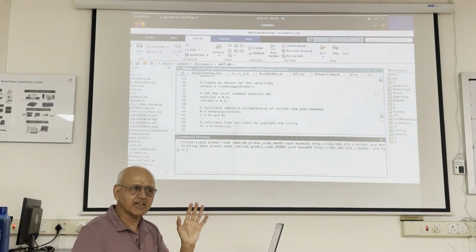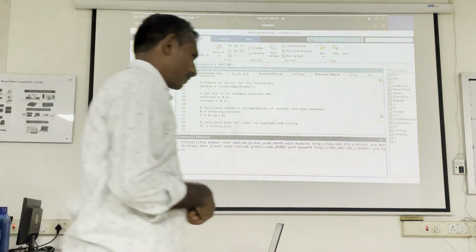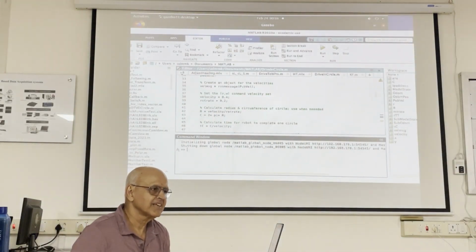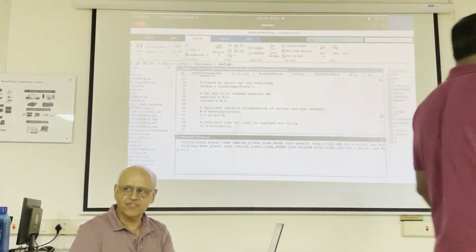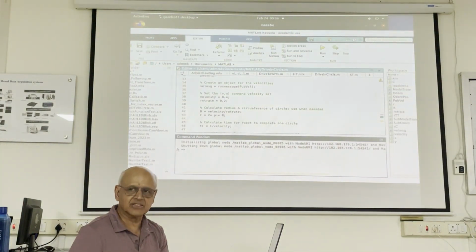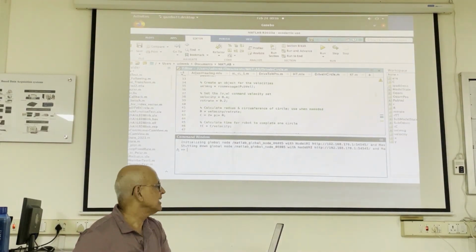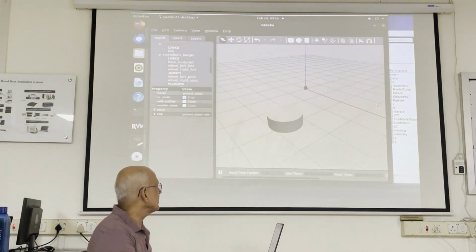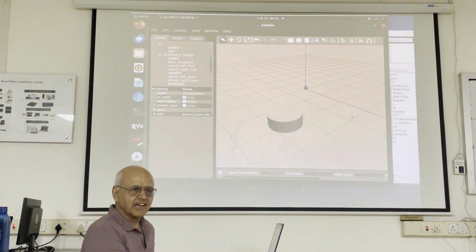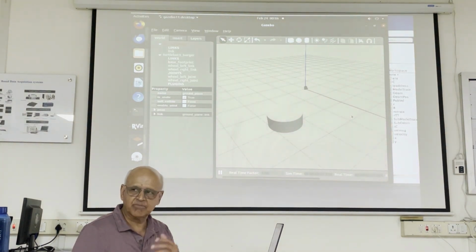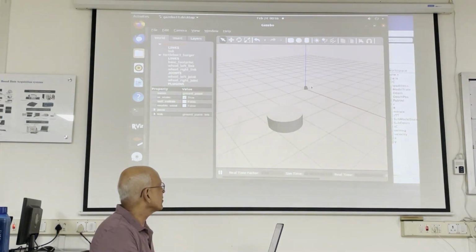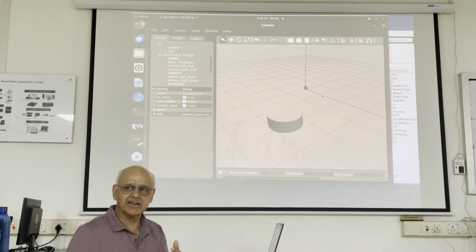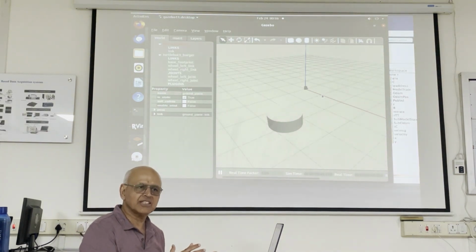But I've seen robots from other companies where it won't run beyond a certain value. It'll start to spin and do crazy things. So try to stay, don't go higher than 0.4, and you can look up the rotational rate limitations. So try to stay within the limitations, but you can take the velocity up to 0.4. The reason I say that is the Gazebo floor is tiled 1 meter by 1 meter. So this is 1 meter by 1 meter. And if this robot is only running at 0.2 meters per second, it's going to take 5 seconds to cross this floor. That's why I doubled it. Because we can't wait forever for the simulation to take place.